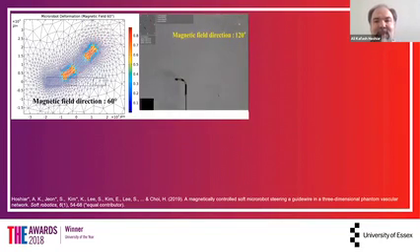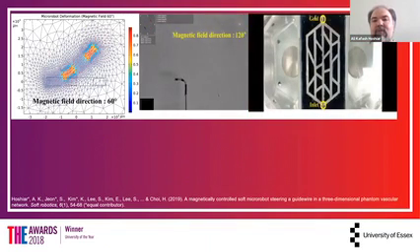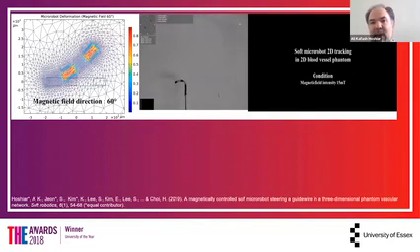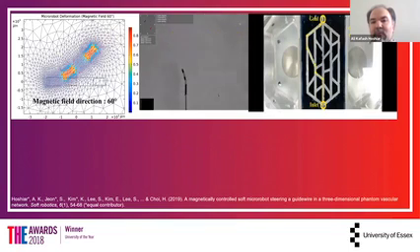And the second step is fabrication. So we fabricate that, and then we show that it is matching reality. It is doing what we wanted to do in the initial step. And then we will do it in more practical, more realistic ways. So here, the goal is to use this complex structure and go from one point to another point using this external magnetic field, moving the macro robot inside this complex environment to reach some goals. And here the goal was opening a blood clot.